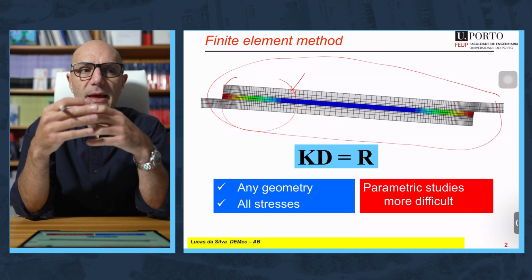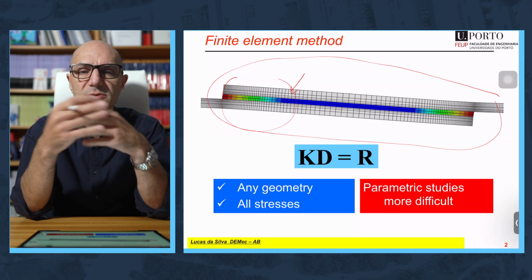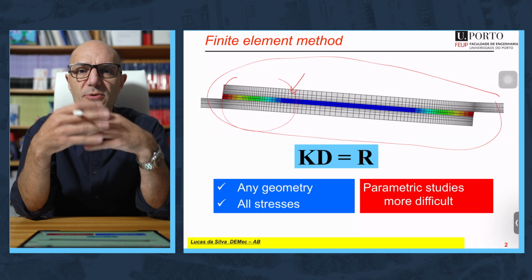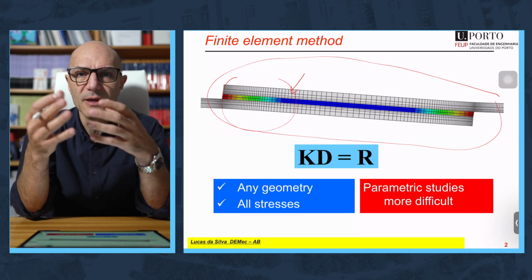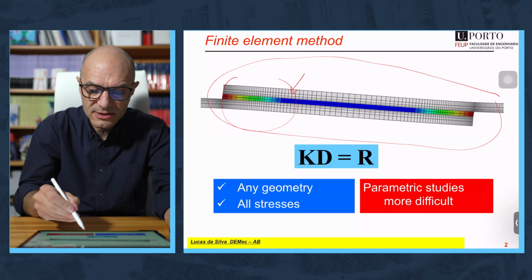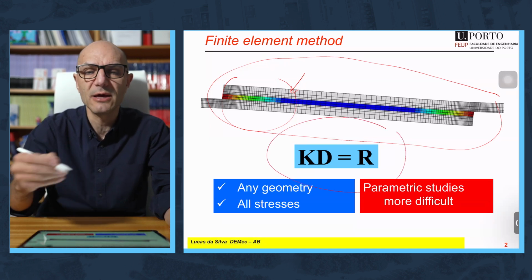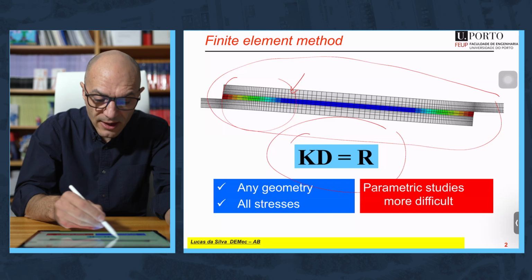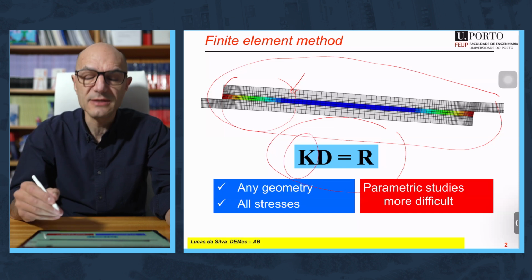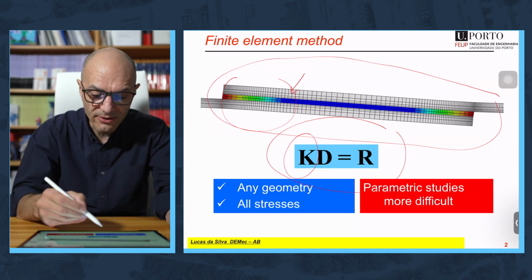One of the methods used to determine the displacement at the nodes is to minimize the energy of the system. This process of minimization generates a system of equations, which in matrix form takes this form: Kd = R. K is the stiffness matrix, which contains basically the mechanical behavior of the element.